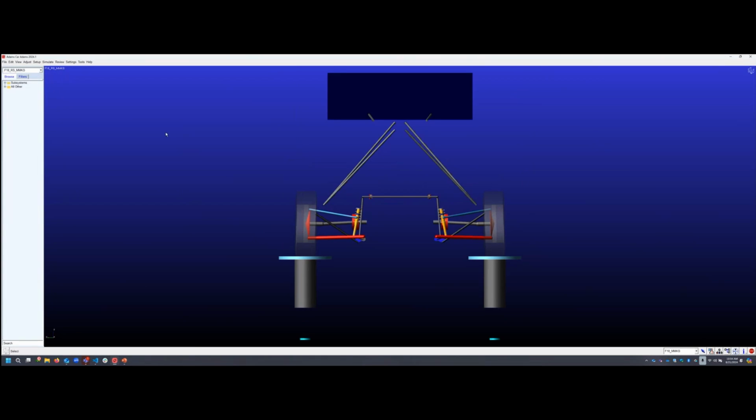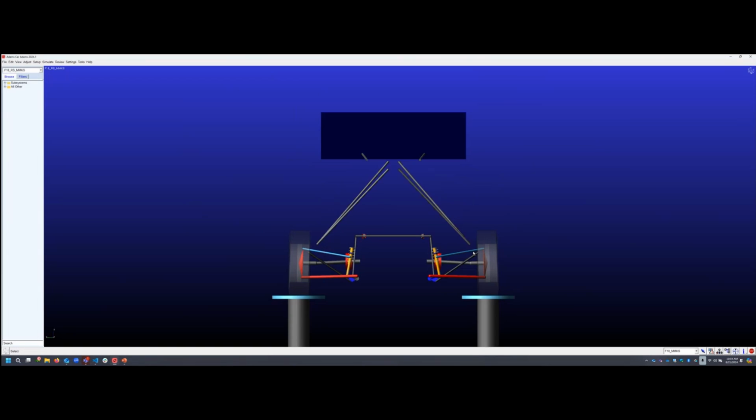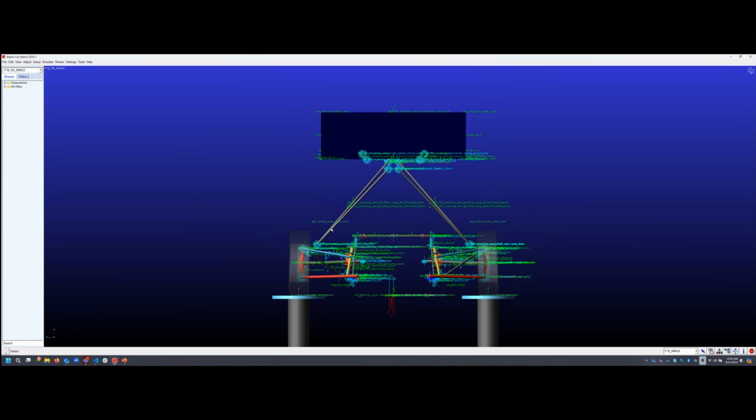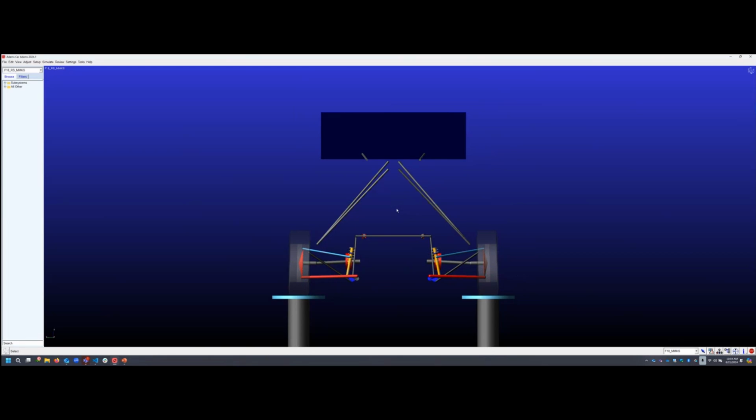For the rear, we had a very similar thing. We are again connected to the suspension here with a bunch of ball joints and all of those things. Of course, the constraints that you're using have to be in line with what you plan to do in the suspension. So make sure that the joints that you're using are right, or maybe you need to use bushings instead of joints. So make sure that you make the right decisions there.